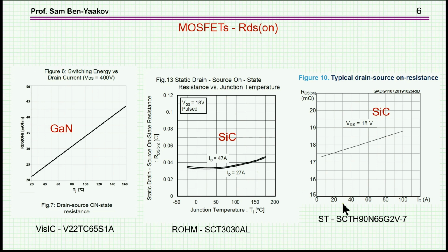So we're going to do what we can with the available information from the datasheet, and I'm going to neglect at this point the change of the RDS(on) with the current. I just assume that it is a function of temperature, period. And of course, the change with current is a refinement that one can add.